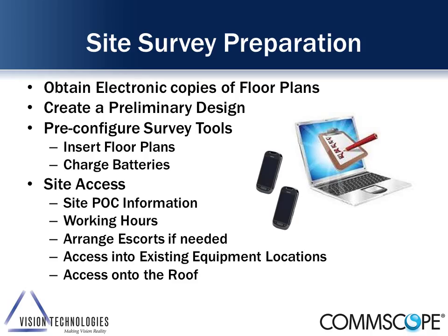And also preparation is making a list of the tools and materials that you want to take on site with you, so you have them when you're out on site. One of the worst things you can do is say, oh, I forgot this cable, and now without a particular cable to connect up the transmitter, you can't do the proper RF survey. So making a list of the tools and materials you want to take with you will help ensure that you have them.